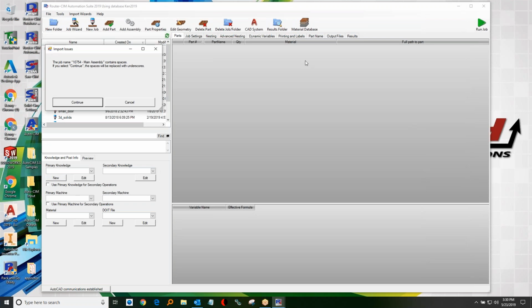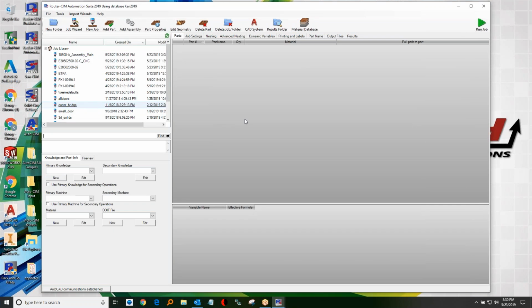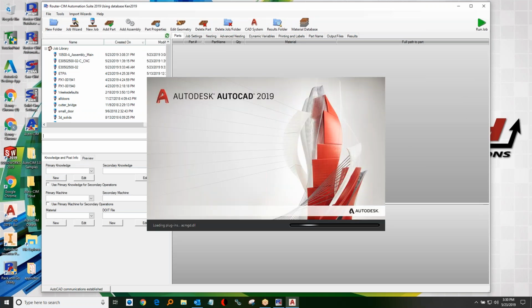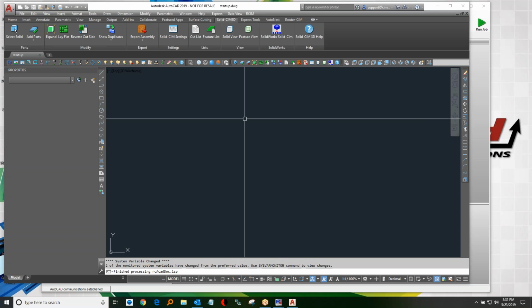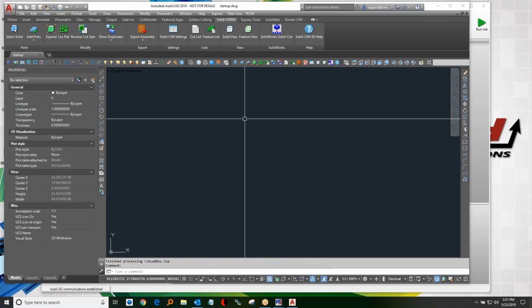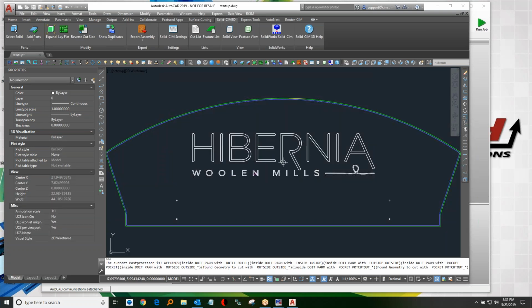It's telling us that we're going to take the spaces and change them to underscores. Your machine will like the underscores better than the spaces. So those layers are on, there's drills on, there's circles on layer drill, there's outside polylines on layer outside, there's pockets on layer pocket, and we look at each layer, make a toolpath, and then make the program for it. And I have a wiki home ag post, so I'm going to get MPR files for each one of the individual pieces, and then for the nested sheets.